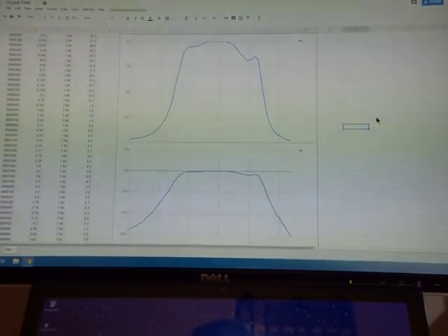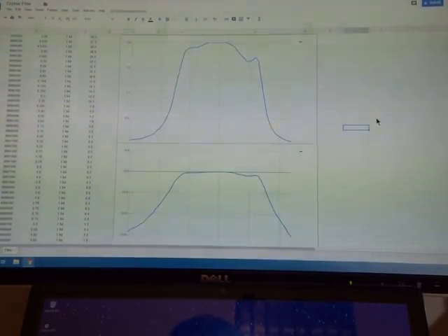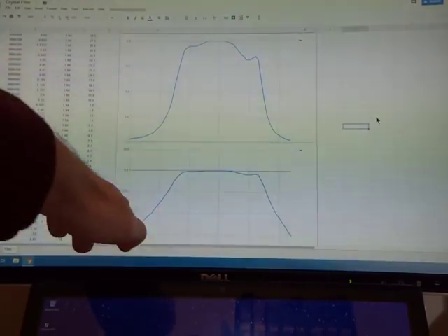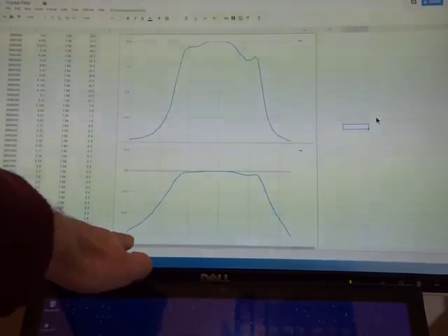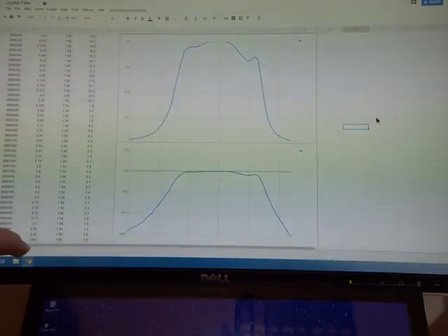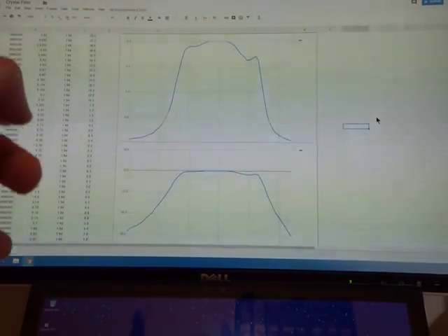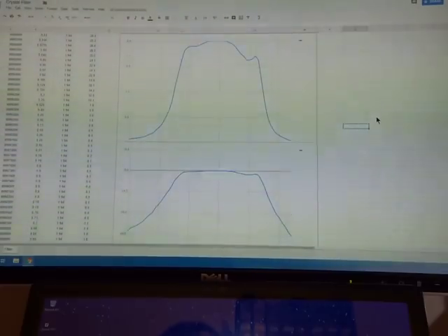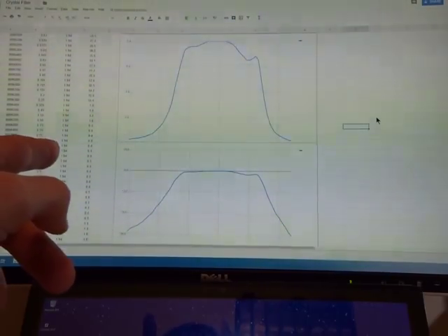The insertion loss also, if my numbers are right, is minus 6.8 dB between what's coming out of the SIG-gen and what's being presented across that 51 ohm resistor. Incidentally, even though this drops down to 30 dB down, if you do go out a couple of kilohertz, that gets down to a good 40 dB. Certainly not 90 dB, that's quoted on some of the commercial filters. Again, I'm not too sure if that's the process I used to measure this.